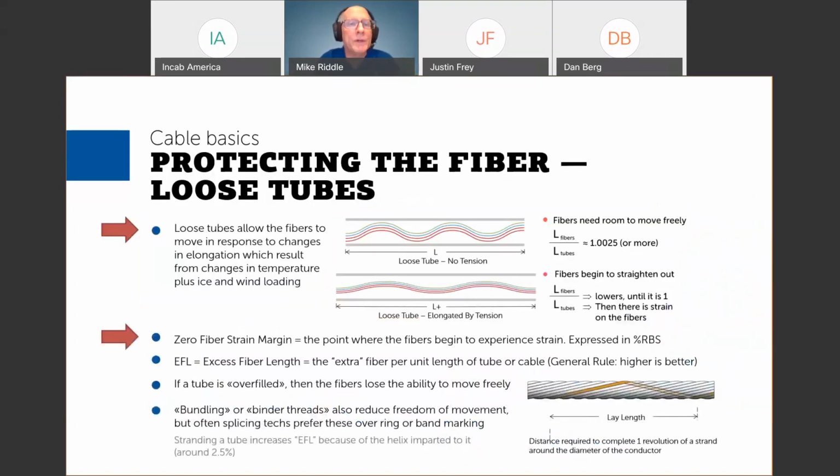So moving from the fibers onto the tubes, these days in outdoor cables, and specifically in aerial cables such as ADSS, the overwhelming majority of cable, again, like on the order of 99%, has loose tube construction. And loose tube is in contrast to a competing technology in the early days called tight buffer. But tight buffer has found it's more applicable in indoor cable applications. So outdoor cables, you generally see loose tube. An exception might be with ribbon cables, but that's another topic for another day.